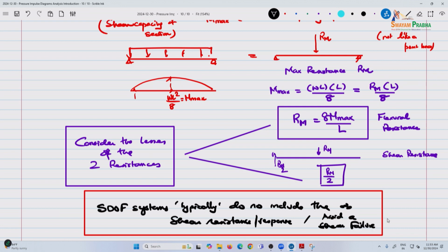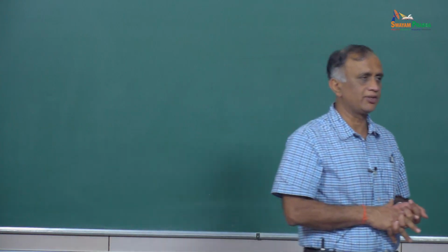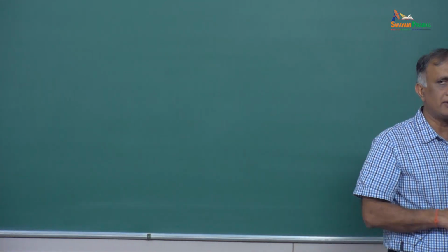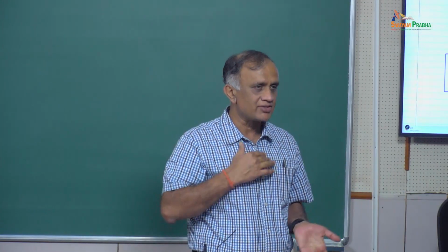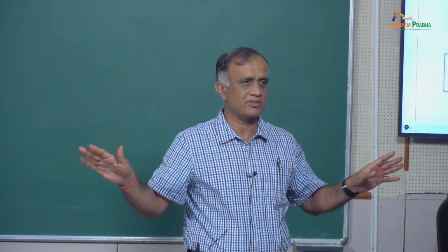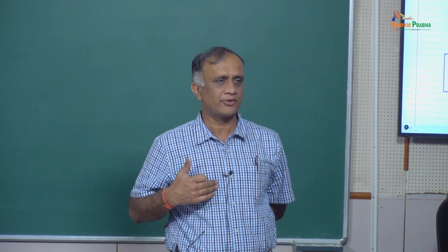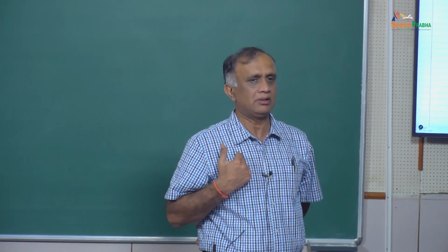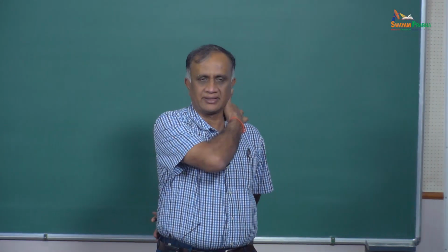What is one of the limitations? If somebody asks you and you are doing a lot of SDOF analysis and they notice that your shear response is often dominating, immediately your work is killed. Nobody is going to accept that, because there is no way you are representing reality.